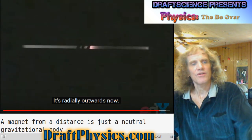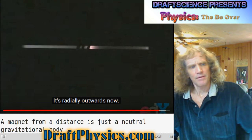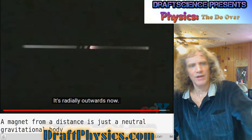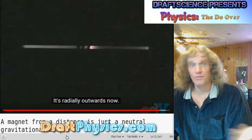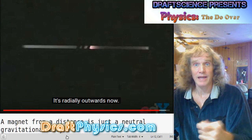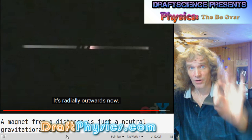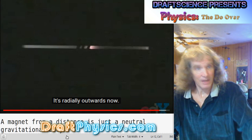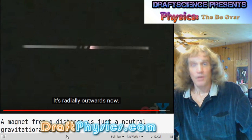So the idea is what's causing this glow, because in theory what's going to happen is there's 100,000 volts at one end and 50,000 volts at the other end. So you have 100,000 volts of difference, which is more than enough to create a light in a fluorescent light. It's obviously the voltage has very low current, very low amperage, so it's not creating much light. So there's low wattage, low lumens.